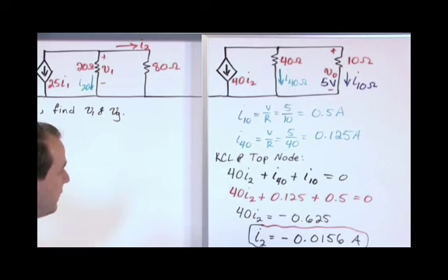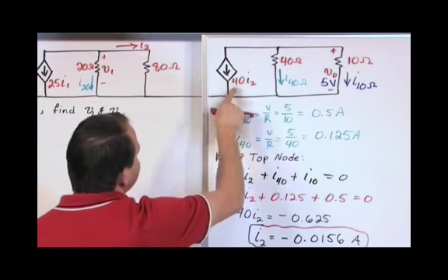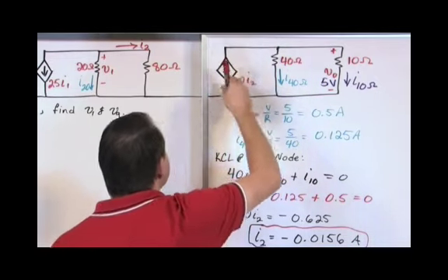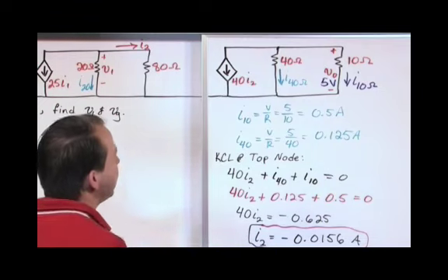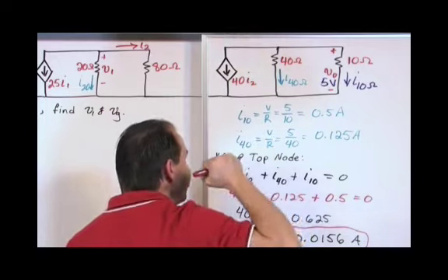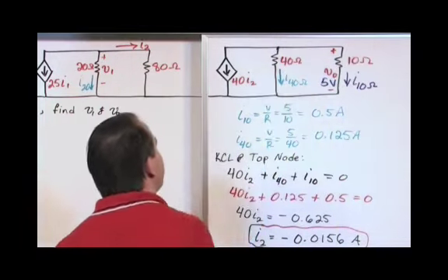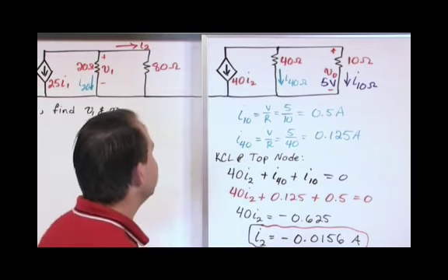And what it also means is since I sub 2 is really negative, this current source, since it's 40 times I sub 2, doesn't really point down. It actually points up. We didn't know that. That wasn't drawn that way, but it makes sense because this voltage drop was given to us, we know for an absolute fact this current is going down and this current is going down. So when you think about it, it's actually impossible for this current to also be going down, because